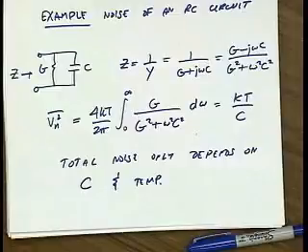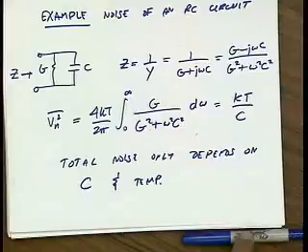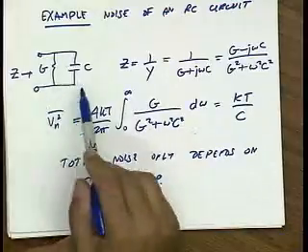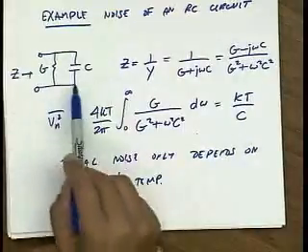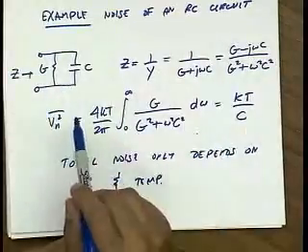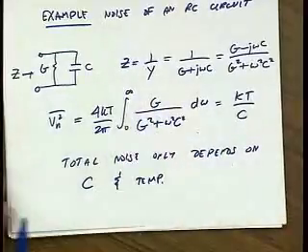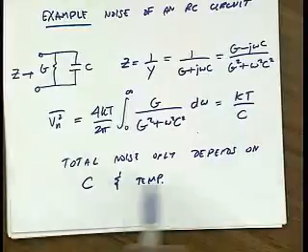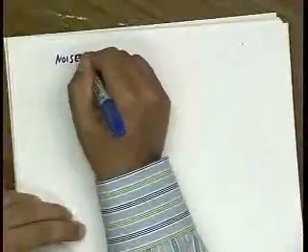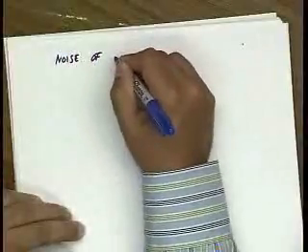If you have a bigger R, then you have more noise at first, but you also roll off a lot sooner. That's right. So basically the effect of the bandwidth cancels out the effect of the noise. We know the RC corner frequency for this is just 1/RC. That's why we call it the RC corner frequency. So if I make R bigger, it seems like I have more noise, but I also have less bandwidth. So they end up canceling each other out. Very good.